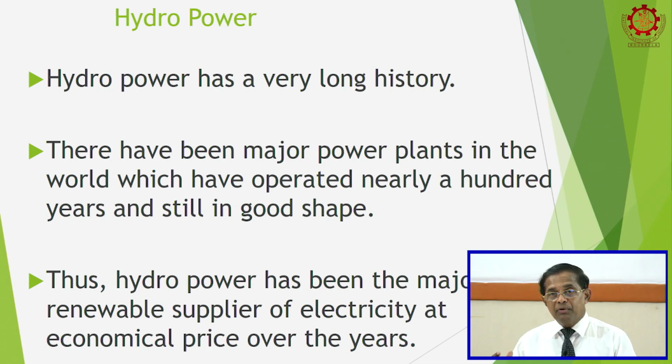Normally mini hydros have plant factors above 35%, some running into 40, 45. Whereas if you take a solar power plant, the plant factor will be about 20% without tracking, with tracking maybe 25%. Therefore, their economic returns are lower compared to small hydropower plants.